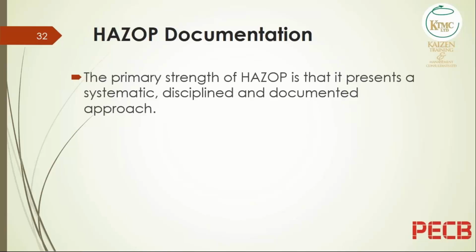I mentioned the documentation earlier, how critical it is. So the strength of HAZOP is that it presents a systematic, disciplined, and documented approach. From the outset, you're looking at what is in place. If you're dealing with an existing operation, you're looking at the P&IDs, you're looking at the documentation of the system, you're examining it, and you're recording the results of your findings as you go along. If it's a new facility and you're looking at the proposed design, again, documentation is vital.